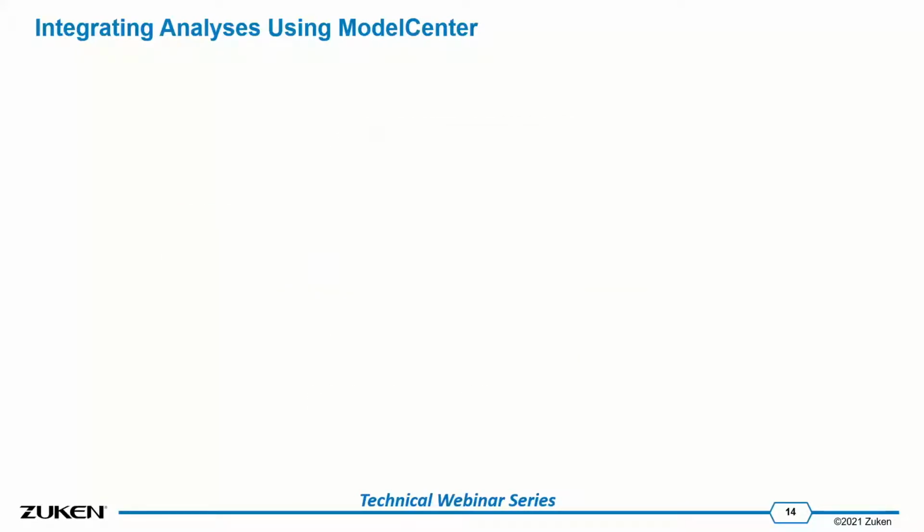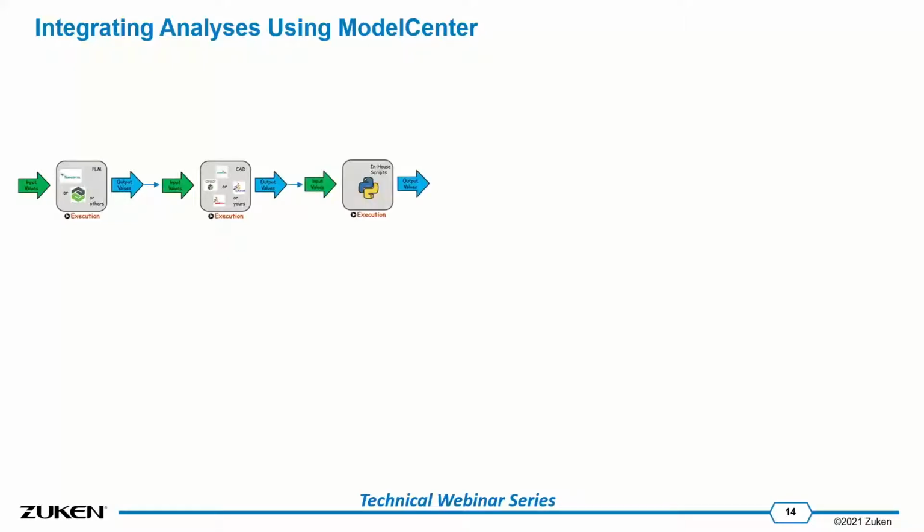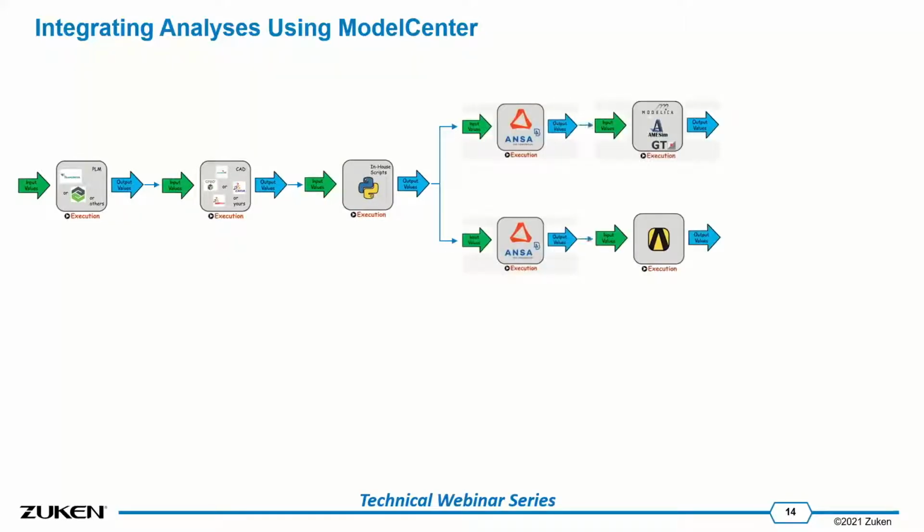Once we have these automated models in Model Center, which can be stored in a library and reused for diverse projects, we will use them to create a workflow. We can think of a workflow as a flow chart in which we connect the different components and execute them in a specific order. So the outputs of previous models will become inputs into downstream models. These workflows can be complex, can contain parallel branches, if statements, and nested components. They can be as detailed as required to capture and mirror the steps that you're currently going through with the manual process.